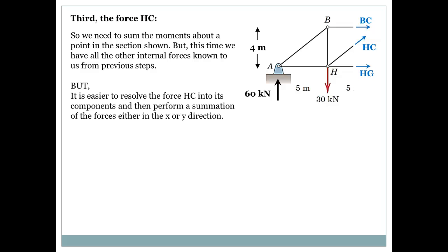Okay, it's easier to resolve force HC into its components. HC will have two components, one in the X direction and one in the Y direction. Then we can use summation of the forces in the X or summation of the forces in the Y to solve for the unknown value of the force HC.